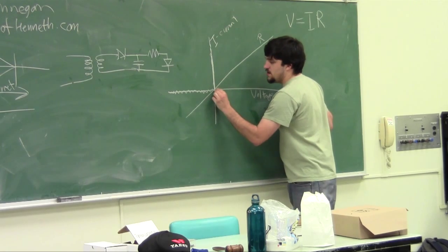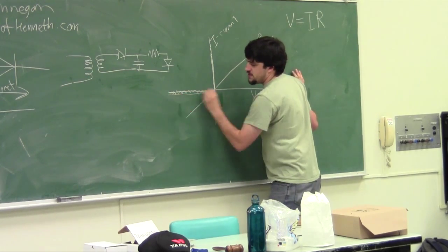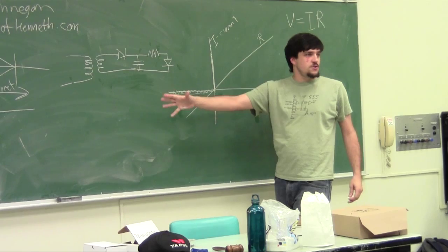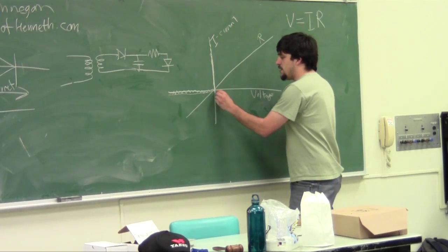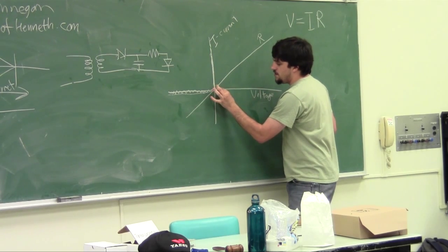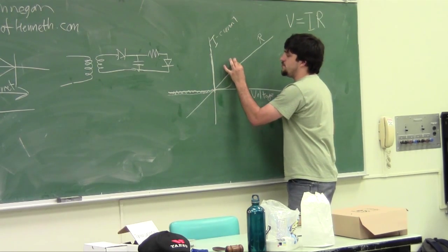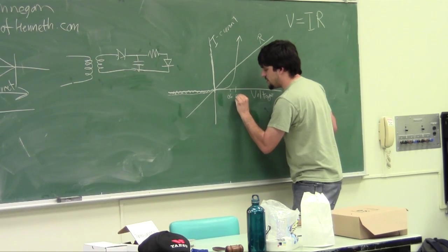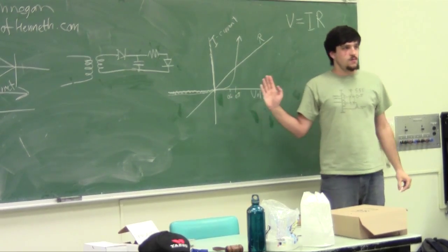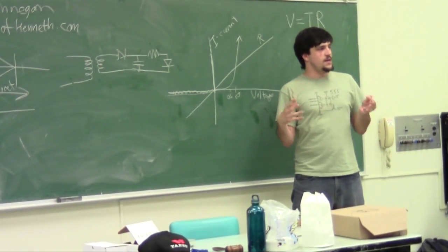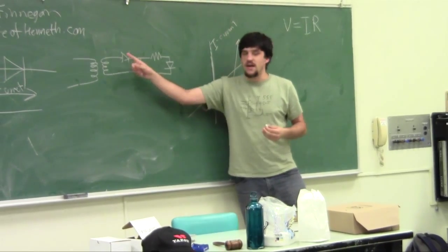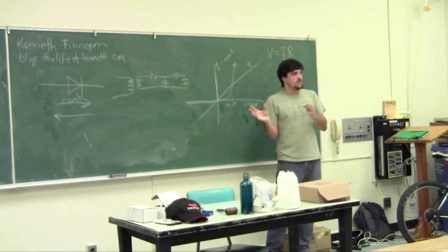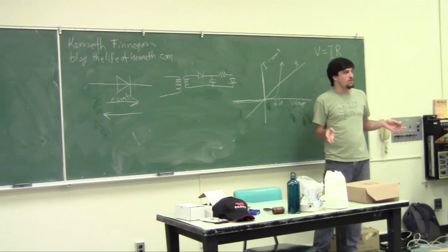Silicon diodes instead have very, very small leakages in the backwards direction. We're talking microamps or nanoamps. So you can usually ignore the backwards leakage, but in the forward direction, instead of it going straight up, the diode doesn't start conducting until you forward bias it at something around 0.6 to 0.7 volts, right? So various people will say, hey, the forward bias voltage, which is the voltage across the diode when it's conducting, is 0.6 volts or 0.7 volts. And you'll always hear these different numbers because it's really not necessarily all of them.